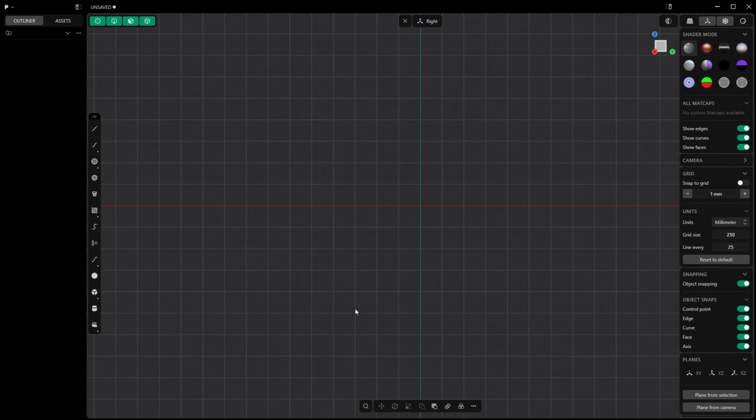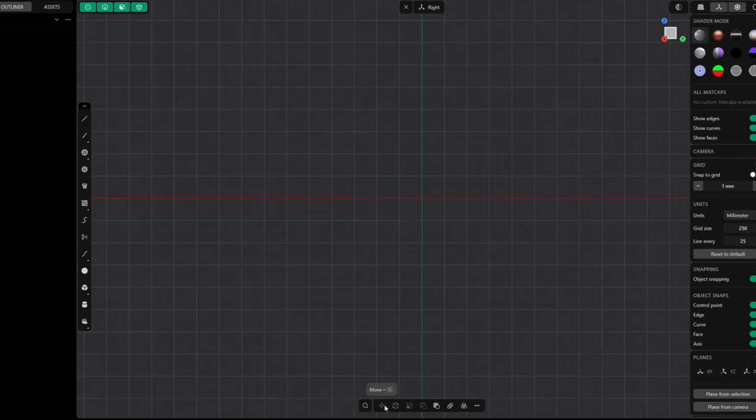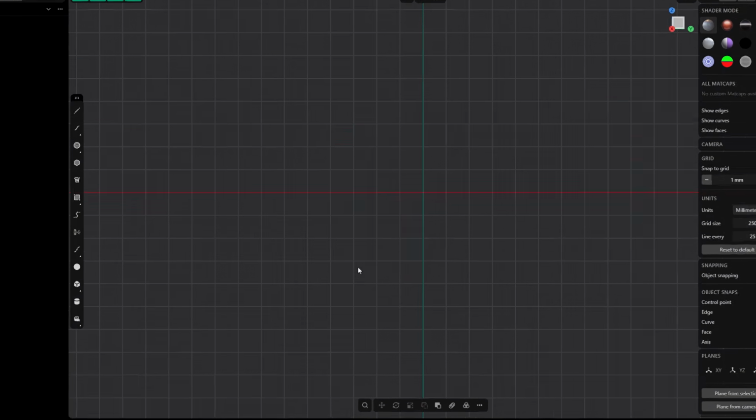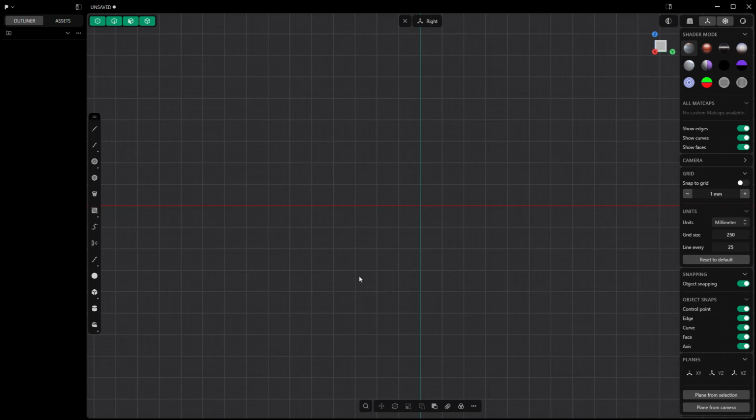That's the numpad on the right-hand side, the numbers across the top for your selection filters, 1, 2, 3, 4, and 5. Also Tab: if you're not creating a solid or curves, Tab will select all of those. And then a handful of things like move, rotate, and scale. Just those alone will go a long way in making Plasticity run more efficiently for you.